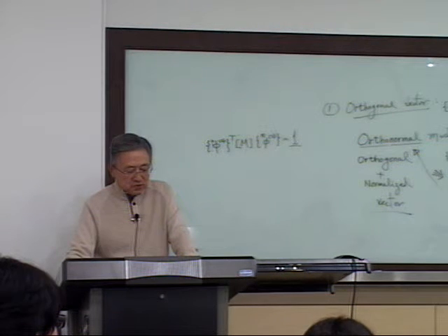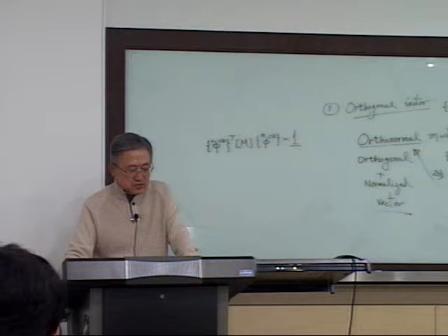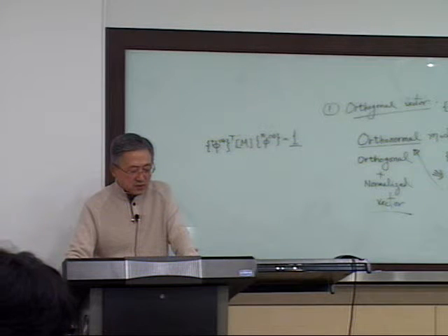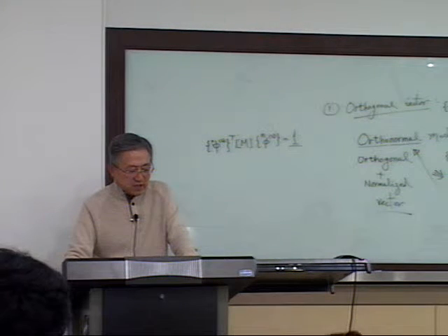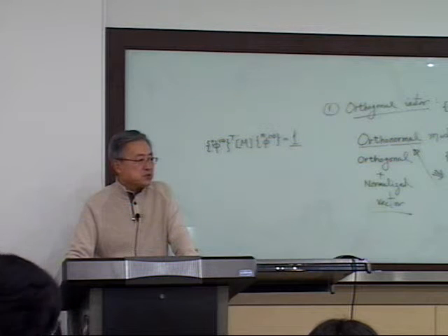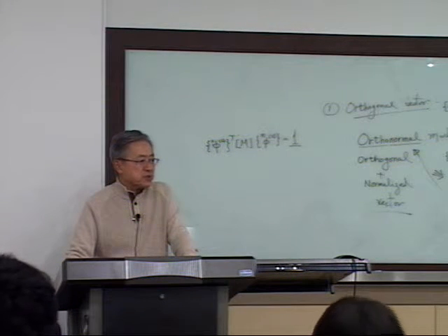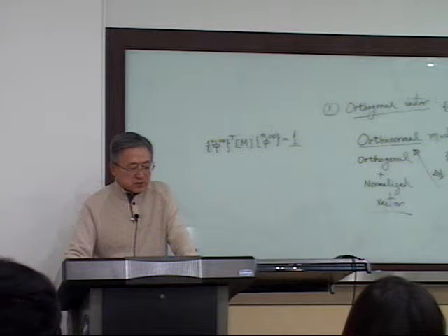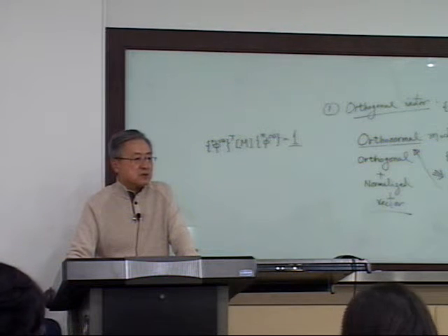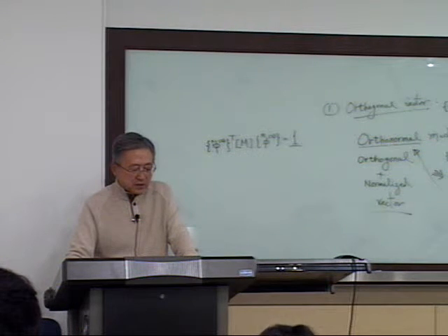And rewrite this here. I didn't give you any proof. Summation over modes, j is a mode, of phi j times P j. P j is the modal participation factor. Always when you take the sum, it is equal to 1. Then rewrite this, and just keep rewriting, then you have this expression.